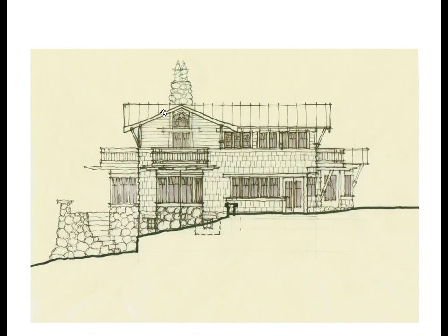That's arguably the eave and the railings up here, and the stone is probably the closest thing in the elevation. You can see here that the lines are pretty thick and pretty bold, and as you step back, they seem to get thinner and thinner. This part of the building over here is further set back in plan than this part, so it's going to be a lot thinner line weight.